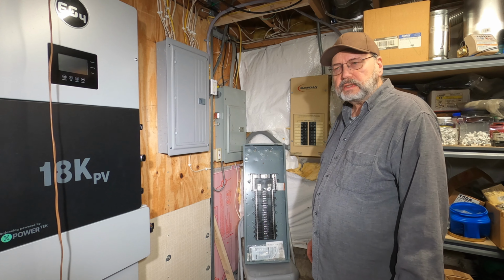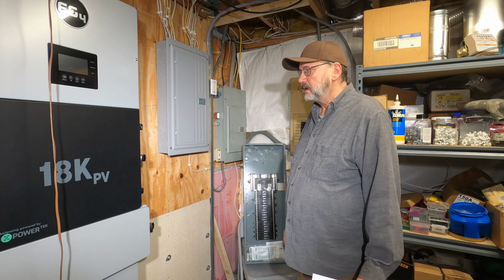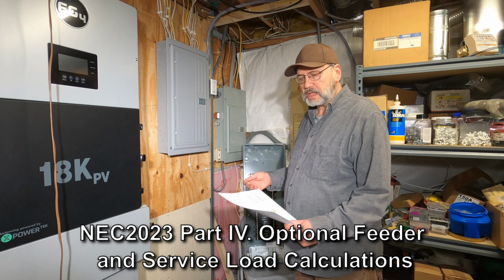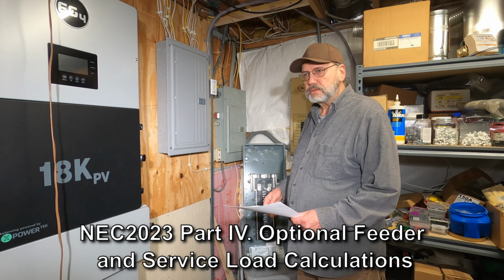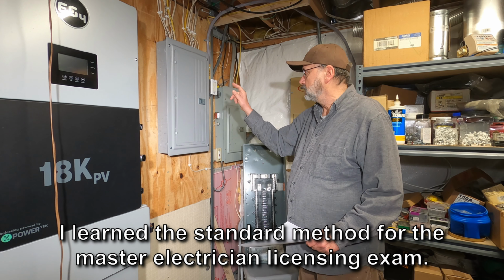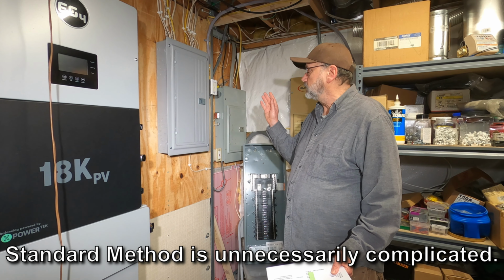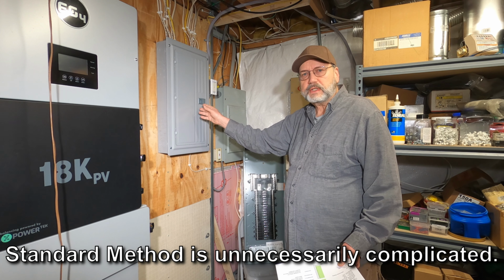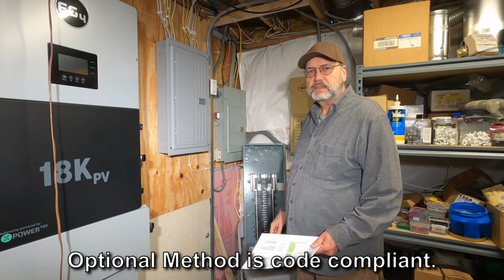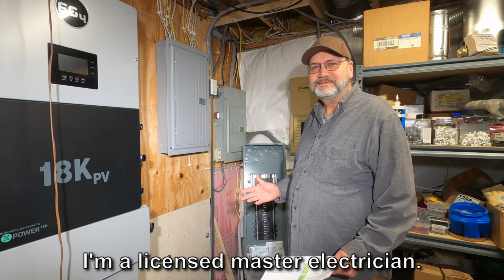Theoretically, anytime you're installing a new sub panel, like I installed one in my garage, I made a video about that, you should do this calculation. It's the optional calculation method for service and feeders. So this is a feeder coming in here. By doing that calculation, you'll know the correct feeder size for the load you're trying to serve with your new panel if you put in a new sub panel. So this applies to sub panels just as well as services for single family dwellings only.